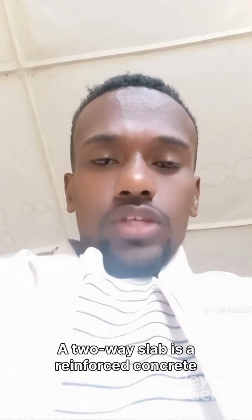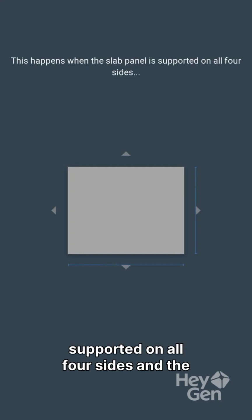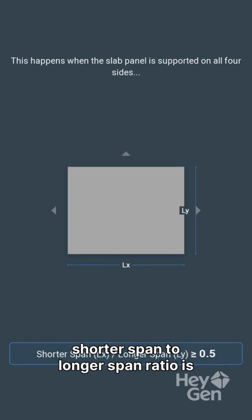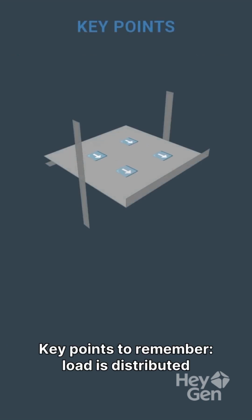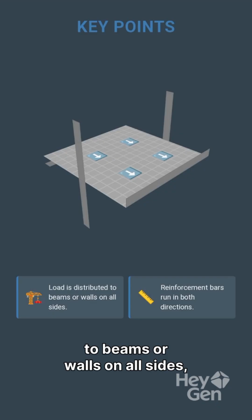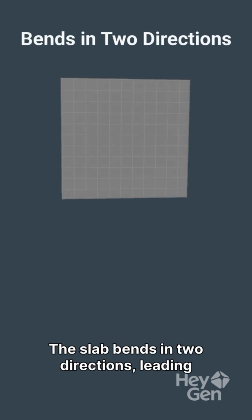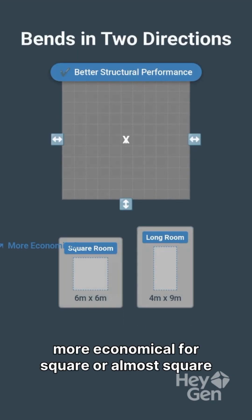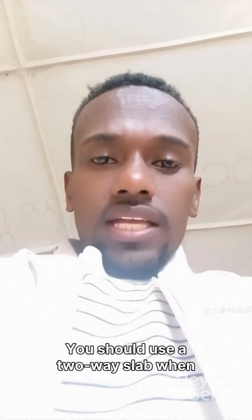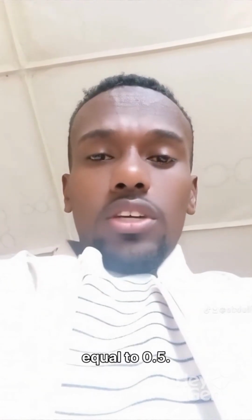A two-way slab is a reinforced concrete slab that carries loads in both directions, both X and Y. This happens when the slab panel is supported on all 4 sides and the shorter span to longer span ratio is greater than or equal to 0.5. Key points to remember: load is distributed to beams or walls on all sides, and reinforcement bars run in both directions. The slab bends in 2 directions, leading to better structural performance, and it's usually more economical for square or almost square rooms. You should use a two-way slab when the ratio of the shorter span to the longer span is greater than or equal to 0.5.